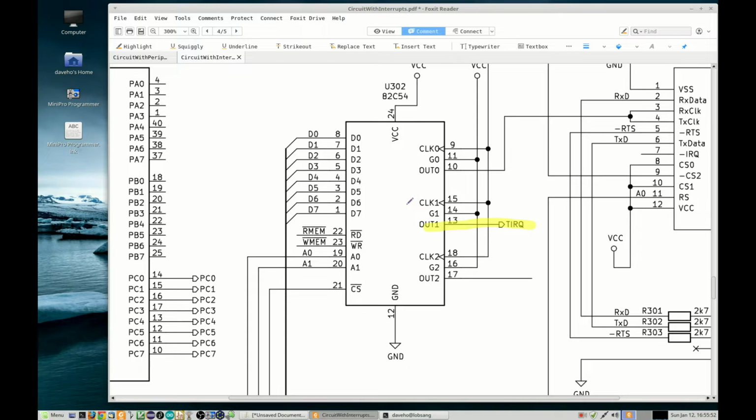And essentially what we are going to do is configure that unit of the timer counter to generate a periodic timer pulse. What we will need to do when we design the interrupt controller is allow it to detect that pulse. Essentially, we need an edge trigger detection mechanism in the interrupt controller such that the edge of that interrupt signal can be converted into a level-triggered interrupt, so that the IRQ signal can be generated properly to allow the CPU to vector to the hardware interrupt handler when a timer interrupt occurs. And we'll talk more about that when we discuss the design of the interrupt controller.